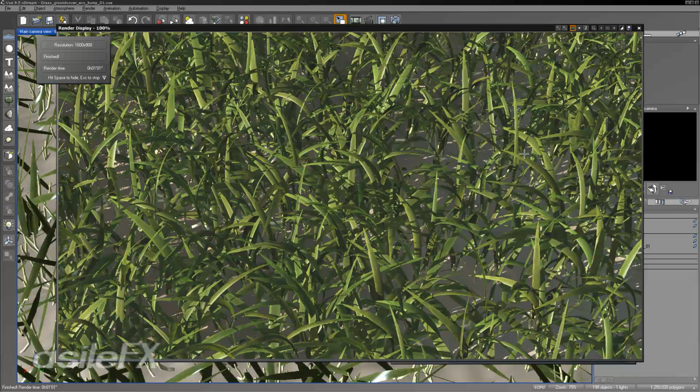It does take longer to render the bump, so it really depends on the situation, how far you are away from the grass and whether or not the scene is animated. So like I was saying, you can basically use this on any single leaf material, provided that the leaf is straight up and down. Try to keep it centered, otherwise you're going to have to go into that Gaussian, the tooth Gaussian, and offset it in its origin in order to find the right center. But there's a lot of flexibility with it, a lot of cool things you can do.